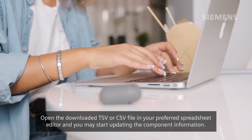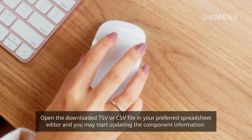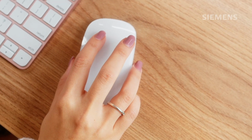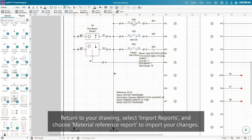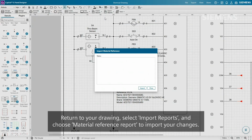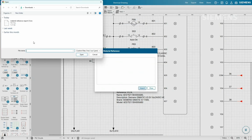Open the downloaded TSV or CSV file in your preferred spreadsheet editor and you may start updating the component information. After editing, save the file in the same format. Return to your drawing, select Import Reports, and choose Material Reference Report to import your changes. Your component information will be instantly updated, reflecting your modifications.